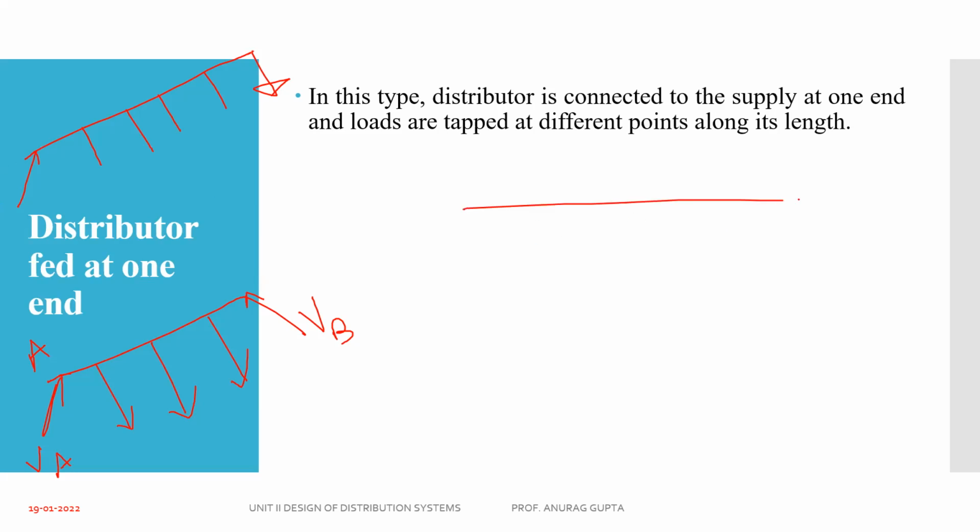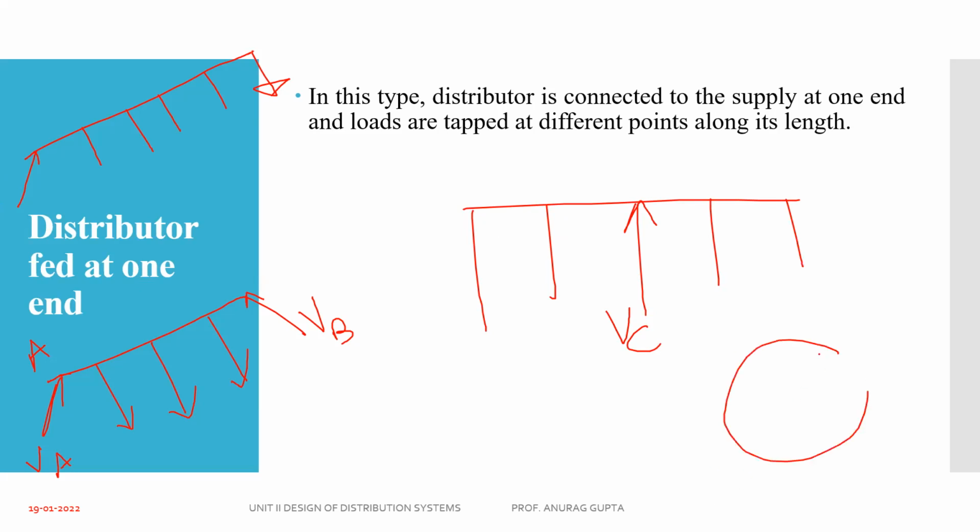What is center? We are providing the feeding point at the center, that is called point C. We can say center voltage, and we are using some consumers on either the left side or the right side. What is a ring distributor? Of course, ring means we are taking a ring system, or we can say an integrated system, and we are providing power like that, and we are using the outer terminals, meaning your consumers will be here. So this is your ring system.